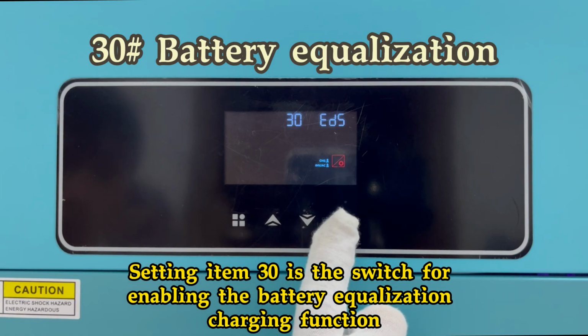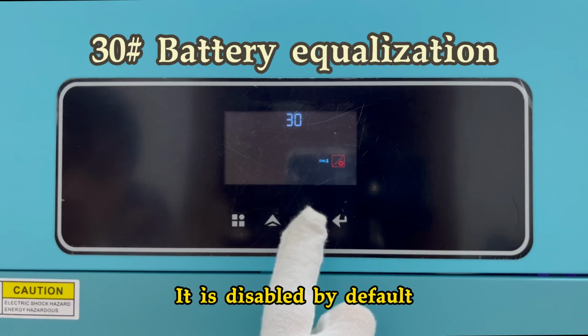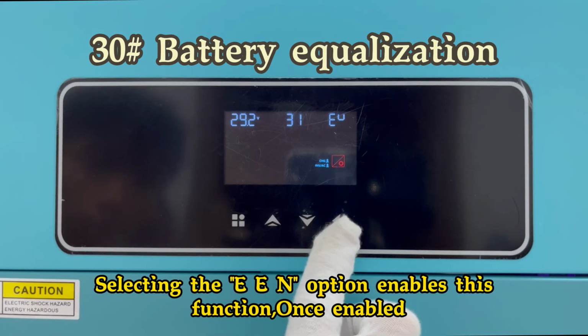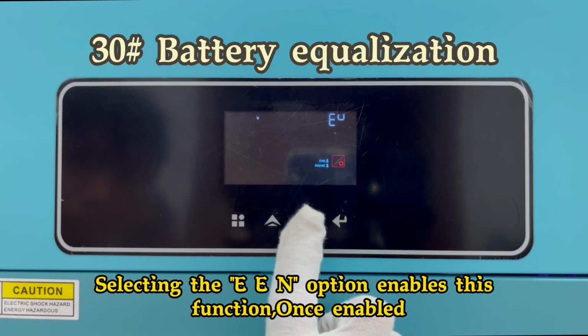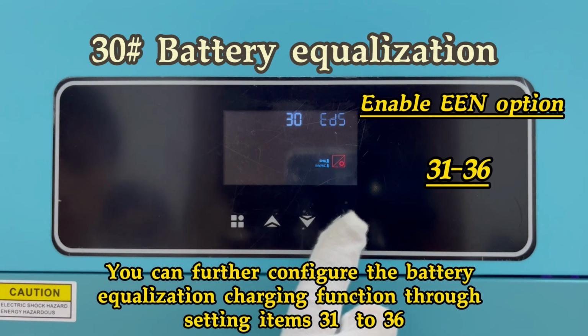Setting item 30 is the switch for enabling the battery equalization charging function. It is disabled by default. Selecting the EEN option enables this function. Once enabled, you can further configure the battery equalization charging function through setting items 31 to 36.